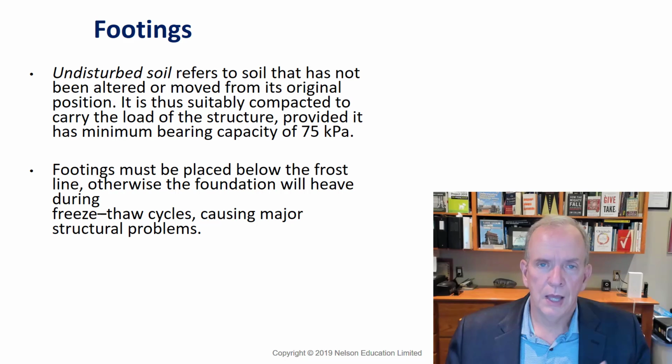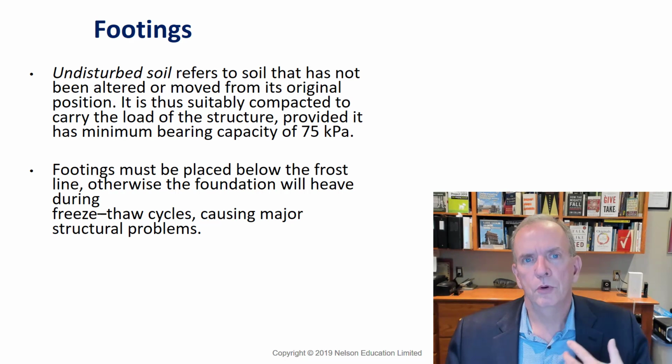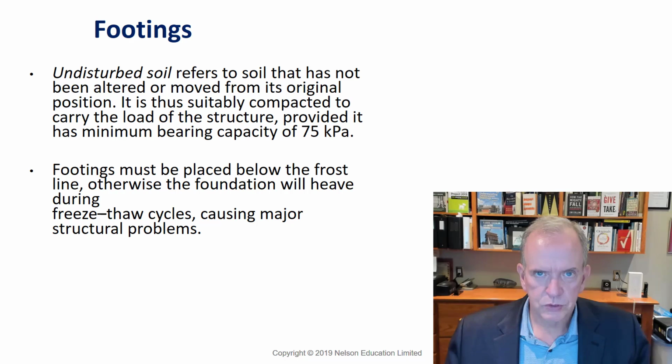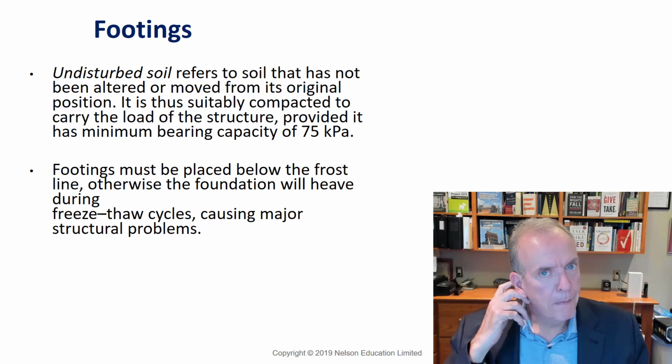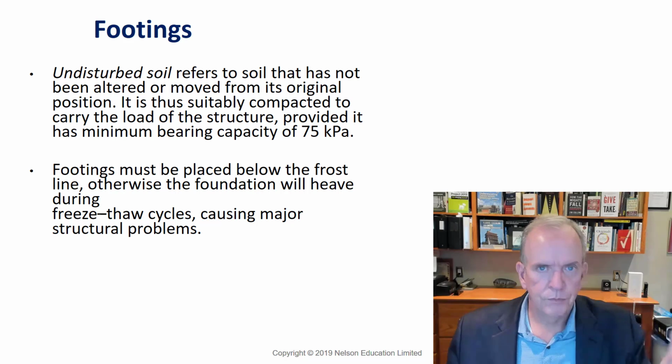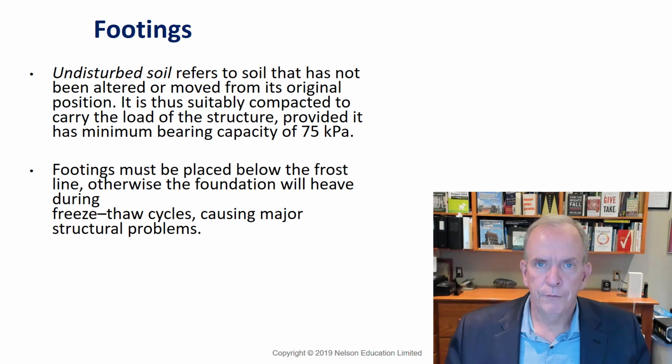That may require excavating deeper. That may require putting reinforcing in the actual slab. That may require excavating out and putting in an engineered fill that is compacted to ensure it has the proper bearing capacity, and the footings and the foundation wall are reinforced with steel. So there's a number of factors that may preclude you from designing under Part 9. But if everything fits those requirements, then footing sizes and wall sizes can be extrapolated out of the building code.